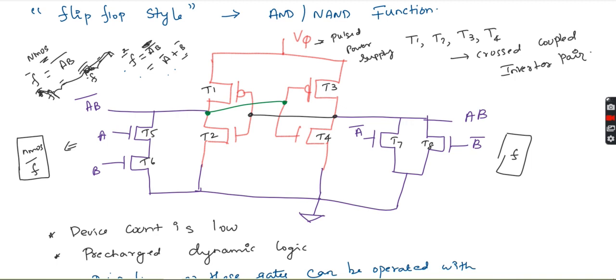Now, all are initially set to 0 volt, the outputs and the inputs of the other gates also. First, we need to provide a set of valid input values that will connect exactly one of the output lines to ground. Since the network implements a complementary function, the supply line will be ramped from 0 to VDD.